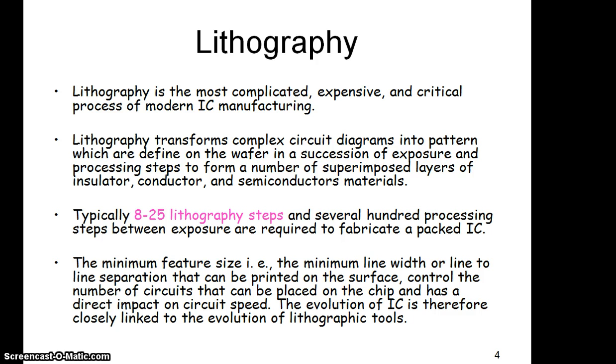It will decide the minimum feature size, the minimum line width or line to line separation that can be printed on the surface. That is going to decide your technology node. The minimum window you can open during lithography is actually your technology, how small your device can be fabricated. This lithography step will decide that.